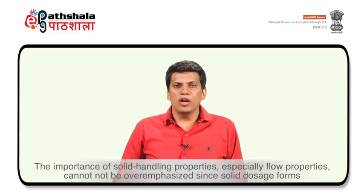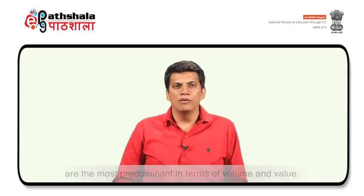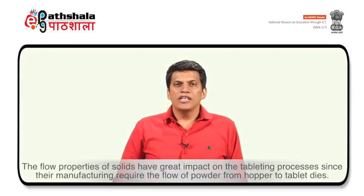The importance of solid handling properties, especially flow properties, cannot be overemphasized since solid dosage forms are the most predominant in terms of volume and value. Given below are a few points to mention the importance of flow behavior. First, the flow properties of solids have great impact on the tableting process since manufacturing requires the flow of powder from hopper to tablet dies.